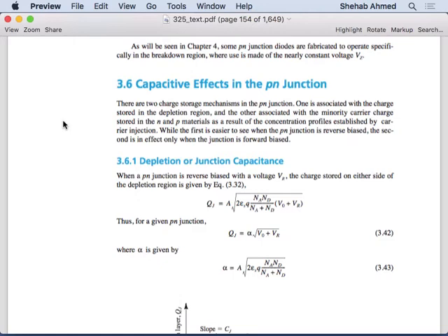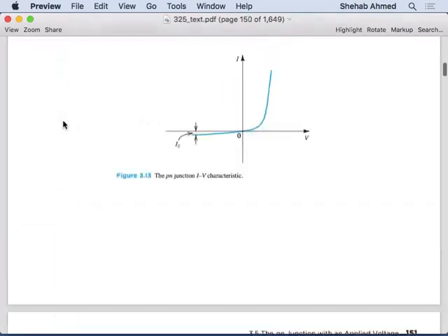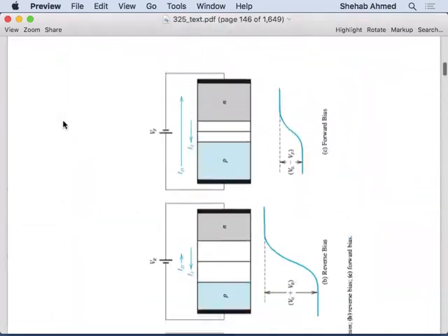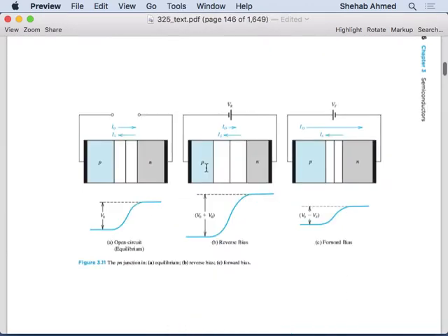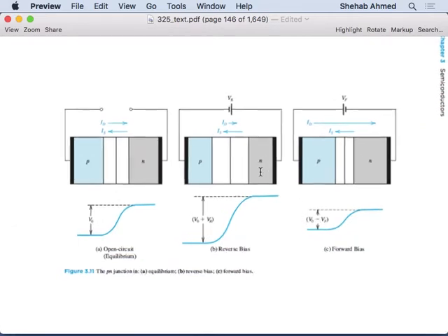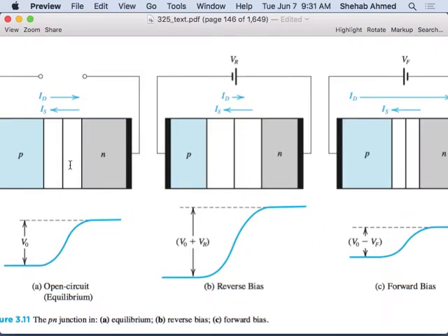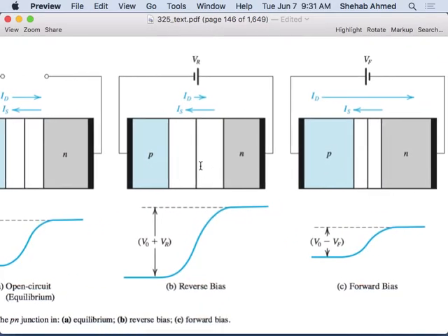How about now you want to go to reverse bias mode, complete blocking, right? What do you have to do? You have to increase the size of the depletion layer again, right? That's what we did. Remember the figure that we had with these diodes? So here, open circuit condition. And then here is reverse bias. Reverse bias, remember the depletion layer increased.